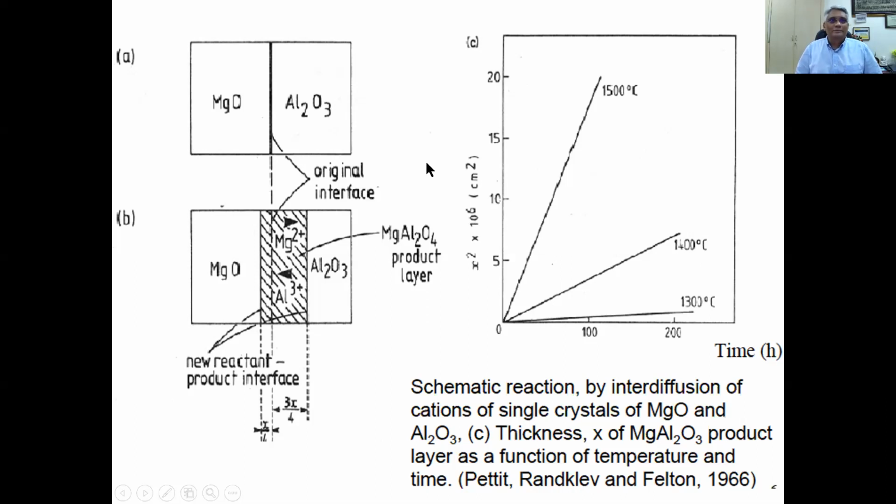Right? Sometimes the phase diagram says if you want to take alumina, Al2O3, and you want to dope alumina with a certain element, the phase diagram may not allow that to happen, which means you cannot dope alumina with a certain element because of the changes in the respective enthalpies of those two systems. Okay, so let's say that a reaction between these cations is feasible, but normally we don't start with the metallic parts of a ceramic like this. MgAl2O4 is a perfect example of a ceramic.